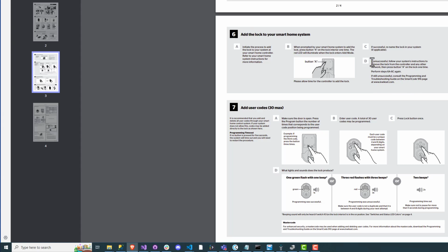And in this case, it's right here on step D. It says press the A button on the lock. And the reason we do this is sometimes the manufacturer will test these in their shop and not reset them. Or maybe you've included it previously. What this step does is resets the lock back to factory defaults so that it can be re-included again.